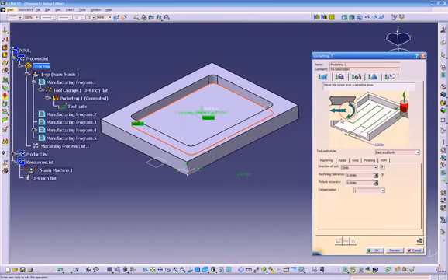So everything is climbing. So I'm pretty sure that all the programmers that are out there know that most of the programs need to be climbing. Rare we find programs that will get a nice finish using conventional. So I very rarely use conventional. I always leave this on climb all the time. I never change it. Over here is the tolerance. You can see over there.